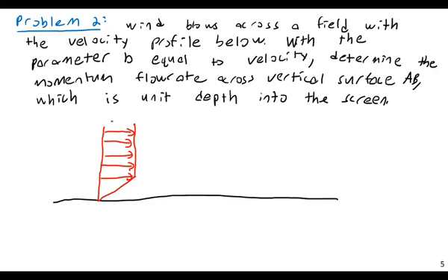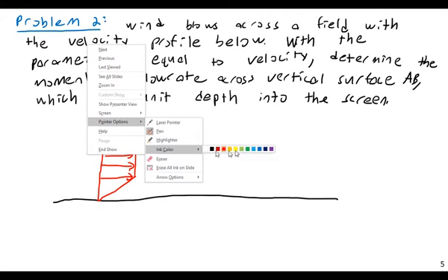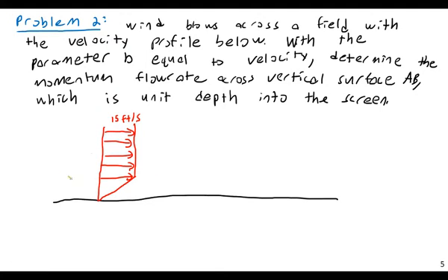And up here, it's 15 feet per second, and then it will decrease to 0 at the ground. 15 feet per second, and then this height transition is at a height of 10 feet. Now this is going to be a simplification of how winds actually behave, but they do illustrate this kind of velocity profile, although they tend to be more parabolic, and more of a smooth function.